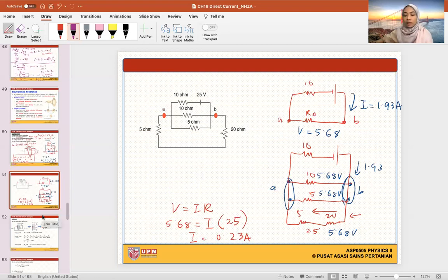Okay, so remember that we calculated the R equivalent for 5 ohms and 20 ohms, which was 25 ohms. Okay, so that was our equivalent for this line or this branch. I'm going to use line or branch. Line means this whole thing. Okay, so 5, 10, 10. So this 10 ohm is not in parallel with this 10 ohm because there's a battery over there. So it messes us up. But the 10 ohm, 5 ohm and 25 is in parallel.